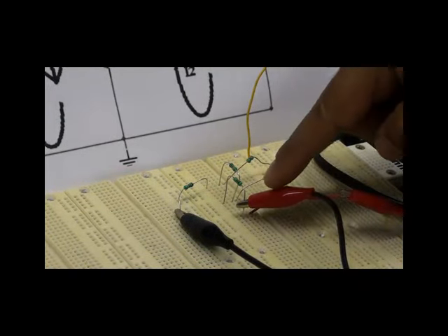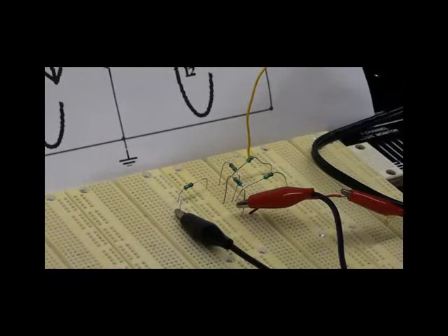Now the current is going through the multimeter, and I can measure the current at R4. So always make sure that you connect the current meter in series. There are two steps: disconnection, so two points have to be disconnected, and then the insertion of the cables from the multimeter right at the points that you disconnected.